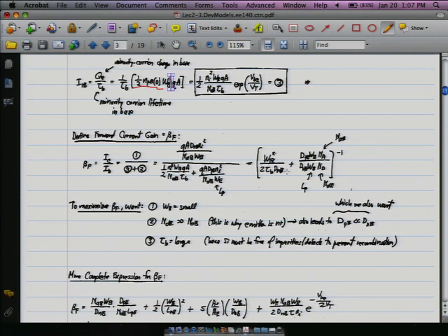So that basically says that, as far as we can tell now, this beta seems to be independent of bias. It seems to be just physical parameters, but we'll actually talk about why that's not exactly true later, because again, we'll come back to this base width.